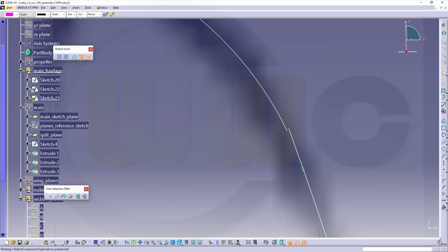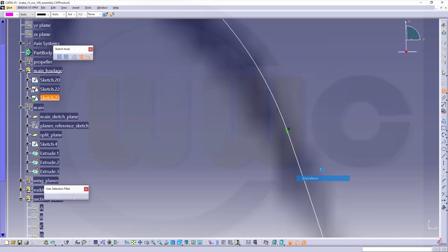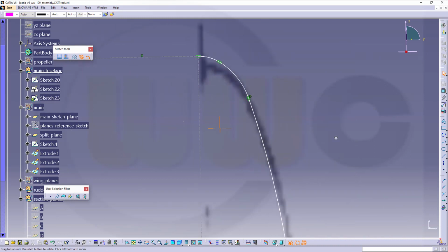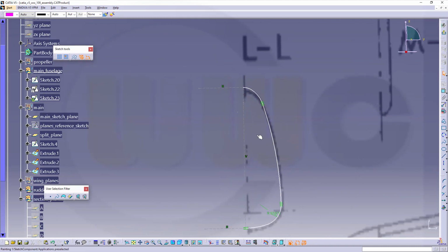See, that's another problem. This point should be aligned with that one here, coincident. Okay, yeah, looks okay. Maybe I should move all a little bit down, but that doesn't matter because I will copy it anyway. So let's go for the selection above geometry. Control C, leave that sketch,